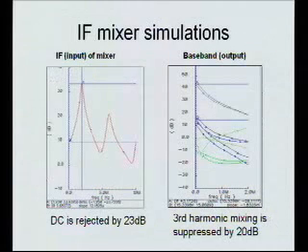So here's the simulation. This is using PAC, which you've all heard about now. This is the filtering effect on the input. So looking into the mixer, you can see it has a nice sharp bandpass that likes the IF, actually likes the third harmonic of the IF as well. It suppresses DC. This is looking at the output. These are those different sidebands that you have to choose from in PAC. So that's the wanted. That's the third harmonic and the fifth harmonic.